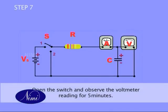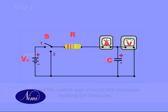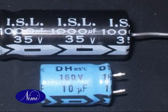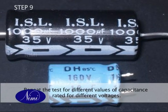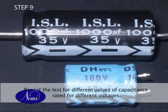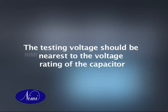Open the switch and observe the voltmeter reading for 5 minutes. Close the switch to position 2 and observe the voltmeter and ammeter readings. Repeat the test for different values of capacitance rated for different voltages. The testing voltage should be nearest to the voltage rating of the capacitor.